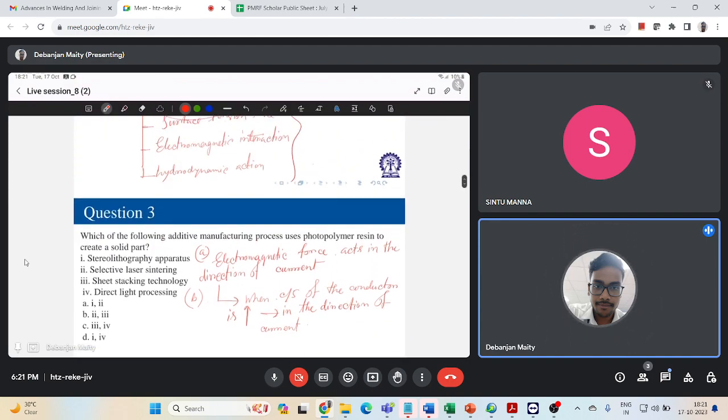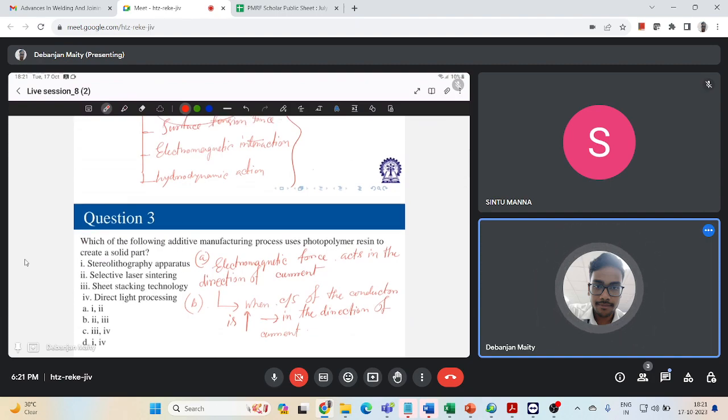So, as I was mentioning, these are my four forces which will always be acting during your molten metal transfer. Now, in the scaling for globular transfer, the droplet continues to grow until the gravitational force exceeds the surface tension force. And as soon as the drop attains a large enough size, and the gravitational force becomes more than the other drop holding forces, at that point of time your drop separates from the electrode tube and is transferred to the weld pool, right?